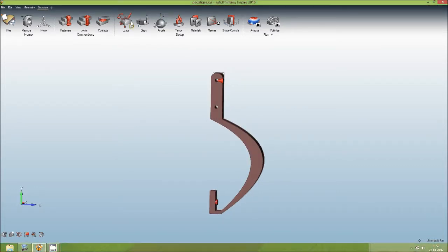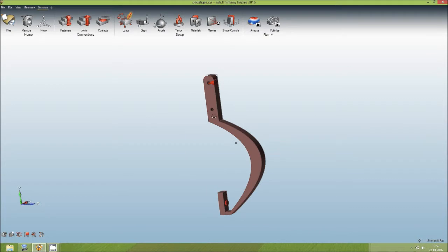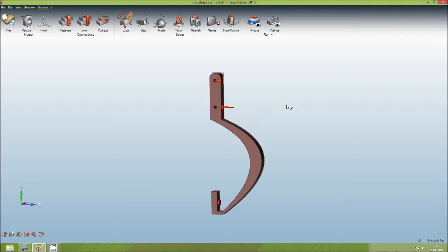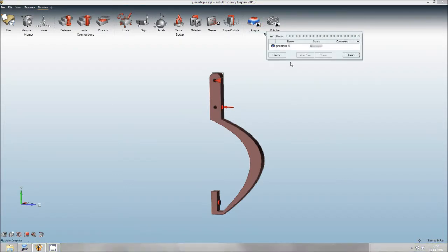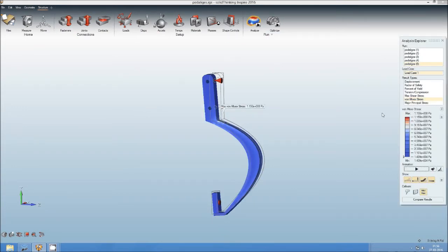I need to apply it over here because it's a pin joint and it won't define a pin joint. Basically we need to create a point. I'm not applying on the circumference, I'm applying in the air, so I think it won't calculate. Oh, so we were applying on the whole part, right? So we need to be really careful.